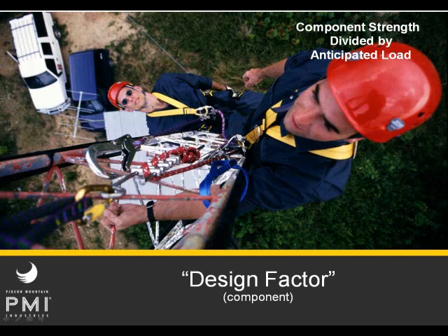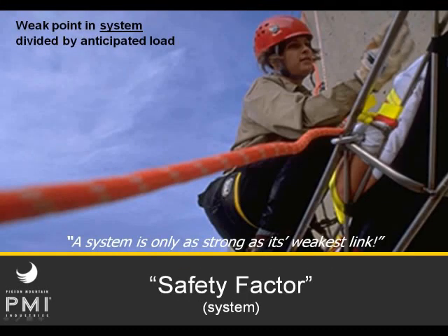This is something of a subjective analysis because it depends on your specific application and use, and it has to be calculated using a combination of education and experience and data. So obviously it takes a lot into consideration and should only be calculated by experienced rope technicians. But when selecting your rope for use, pay more attention to your system safety factor than you do your component design factor. Your safety factor is your weak point in your system divided by your anticipated load.